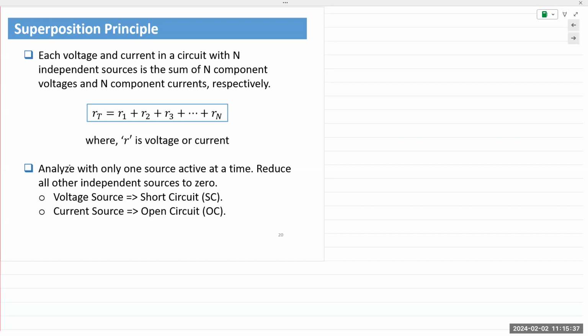The concept comes from this. Let's say we have a voltage source connected between points A and B. And this is Vs. So voltage measured between A and B is simply equal to the source voltage Vs. So now I'm simply explaining why we replace it with a short and open circuit.